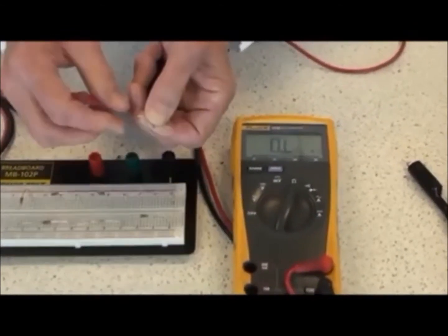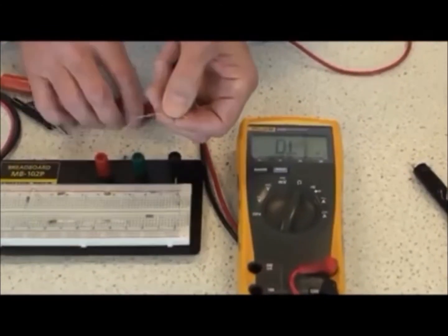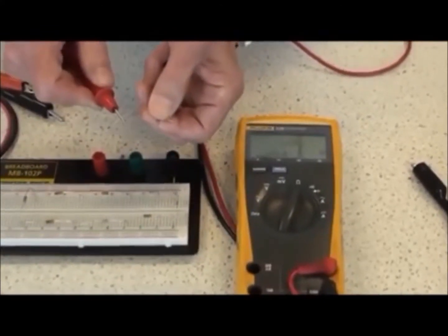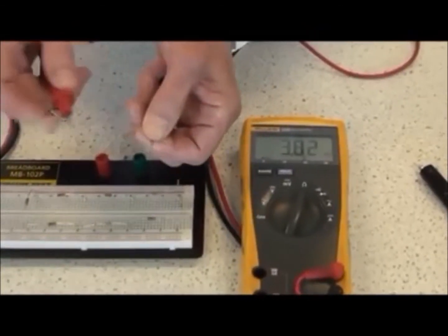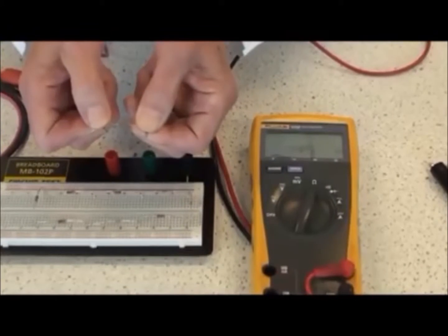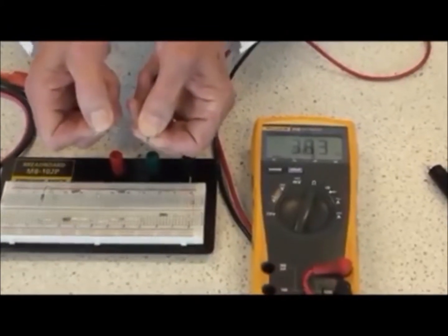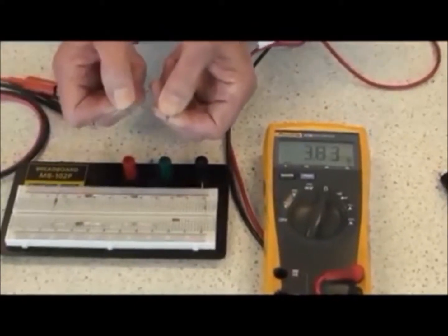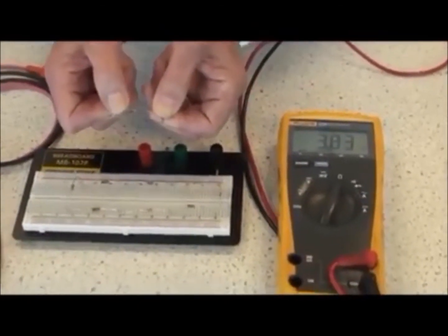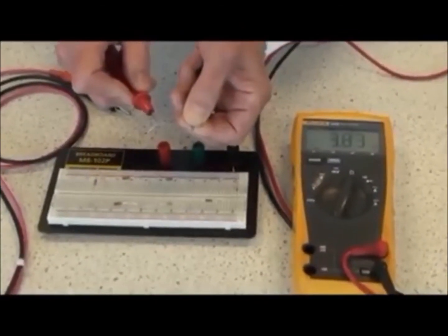It doesn't make much difference for smaller values of resistance. I've got a smaller value of resistor here, 3.83 kilo ohms, and if I hold both sides of this one, you read very much the same number. In fact, this is the same number. So the higher the value of the loose resistor you use, the more effect there is from holding both sides of the component.